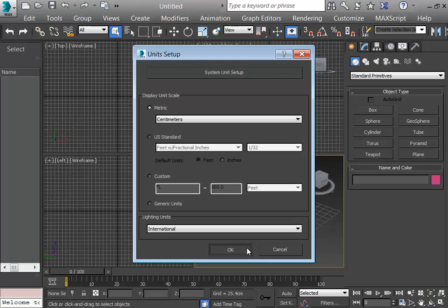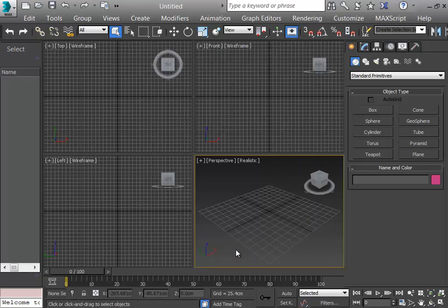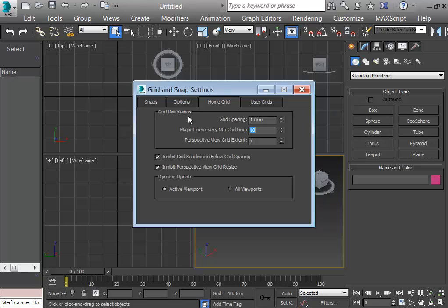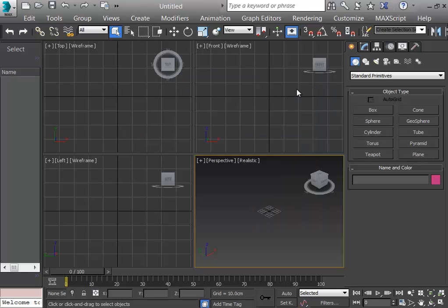That's okay. What I'm going to draw is just a flower pot with the flowers, so it is not a big object. I'm going to change my grid setups. In here, by right clicking, I set the grid spacing as 1 centimeter, and I want to see the major line after every 10 centimeters. And I want the size of 30 boxes in every direction. Again, the grids are not the matter for me in your exam. Either way you prefer is acceptable for me. Okay?